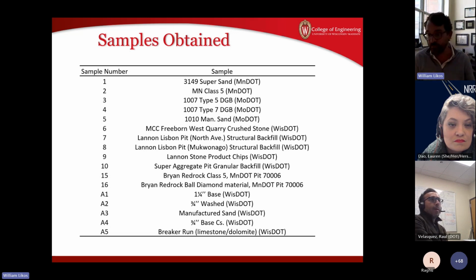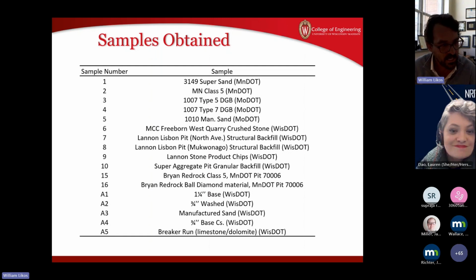Well, I certainly think we should be. I've spent most of my time dealing with unsaturated soil mechanics, and I am constantly trying to find ways to integrate unsaturated soil mechanics into practice. That was really what drove this project. Let's recognize that for drainability, the soil water retention curve matters, yet it's difficult to measure, and for that reason, very rarely measured. Can we lower the bar a little bit? Can we say, all right, well, let's try and indirectly integrate unsaturated soil mechanics by doing things that we're already doing, like measuring grain size, for example.